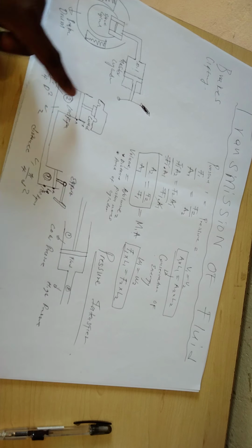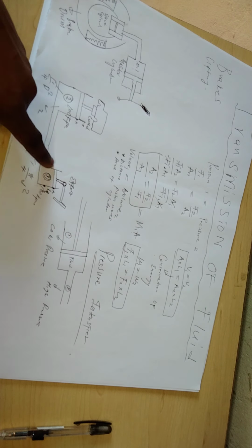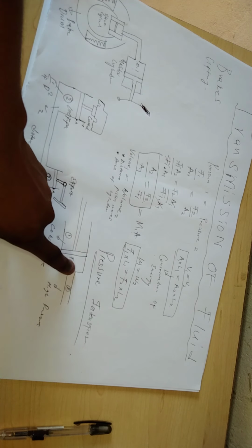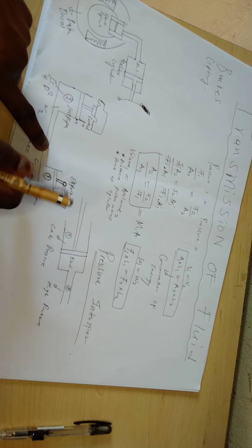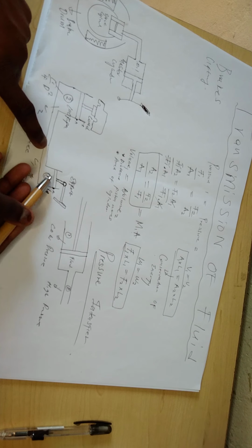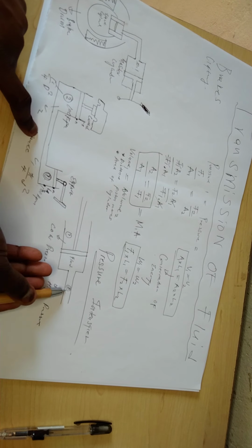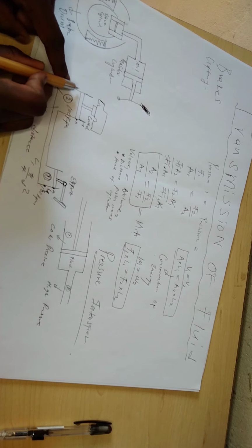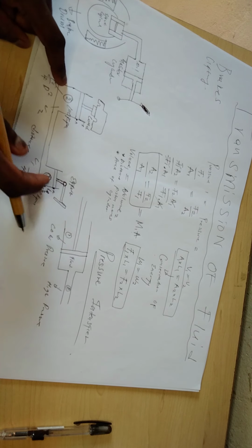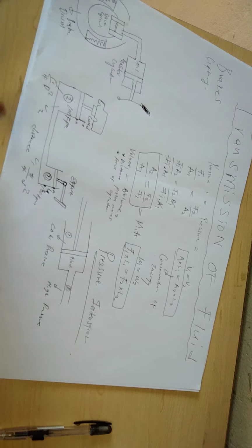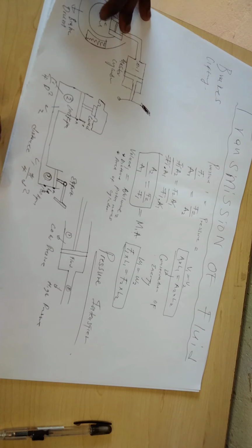For example, here on the effort, they're going to install the pressure intensifier. So it means you're going to have 3 areas: the area of the intensifier, the area that you're going to get here onto, and the area of the RAM over here, the area on the load. You're going to have these 3 kinds of areas. So familiarize yourself with something like this.